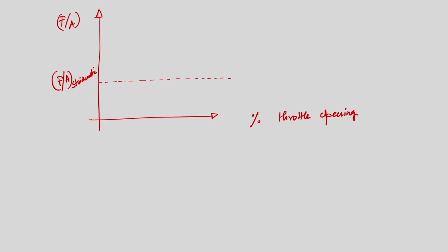As we can recall, when we need to supply maximum load, of course, the throttle will be fully open, and we have seen during the idling zone the engine is running but supplying no load, so the throttle valve is almost closed but not fully. So, this throttle opening, or I can say this is load, is along the x axis.